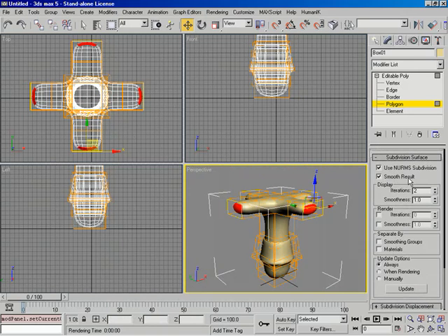First of all, smooth results. What this is going to do is put my final geometry all in the same smoothing group, so that nothing's faceted, everything's nice and smooth. Next, we've got two groups, a display group and a render group. This is really important when you start dealing with very complex geometry. The display controls the way that you see your high-res geometry in the scene while you're working, and the way that geometry appears when you render it when the render checkbox is not turned on down here.